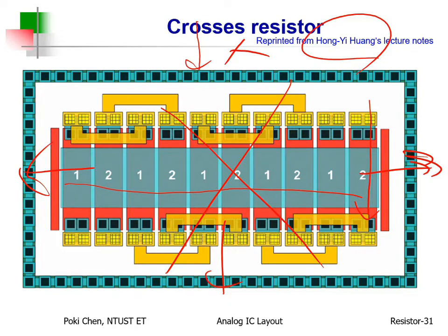Upward and downward. So what you can do, especially for downward, there must be a substrate. We hope you don't interfere with the substrate too much. What you can do is put some kind of shield below the noisy resistor. Unless it uses something like P-type, then it will become much less noisy.